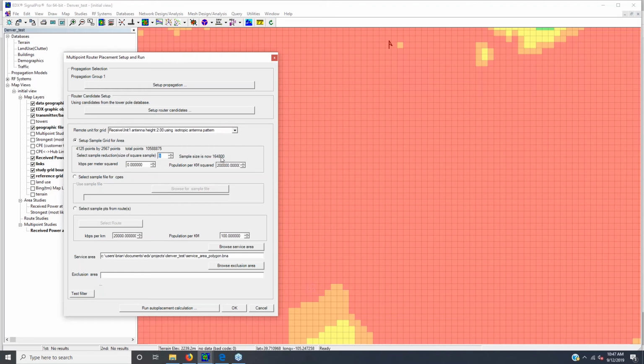You notice that's kind of my cutoff, where if I'm getting up to 400,000 target points or so, I just don't want to wait for that many path loss calculations. So I'll sample this down, and it'll take chunks of these study grid points instead and make one chunk of 8 points as a target location instead.